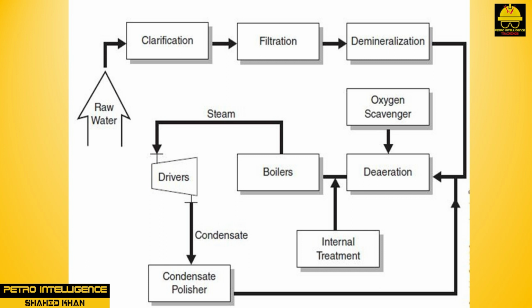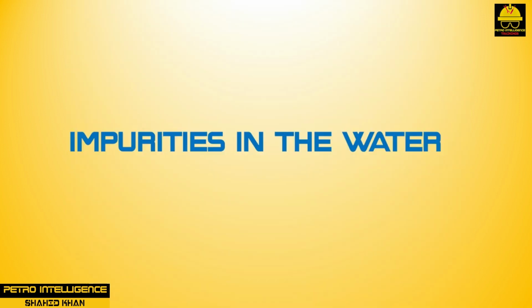2 or 3 pumps are used in the pump-around operation. The primary pump typically has 1 or 2 backup pumps that are placed in standby mode. It is essential that all impurities be removed, otherwise harmful scales or excessive corrosion will occur in the boilers. High concentrations of dissolved solids in boiler water will cause foaming of the water within the boiler. Foaming produces carryover of impurities in the steam, resulting in deposits on the turbine wheels.